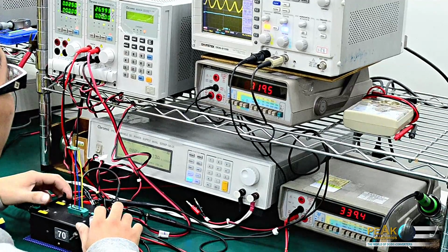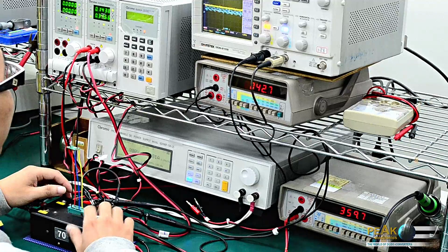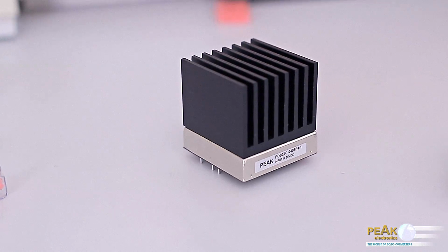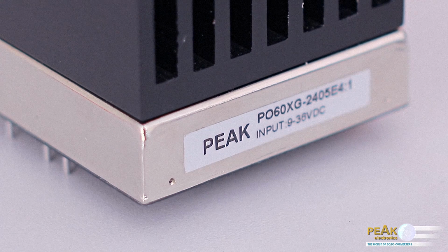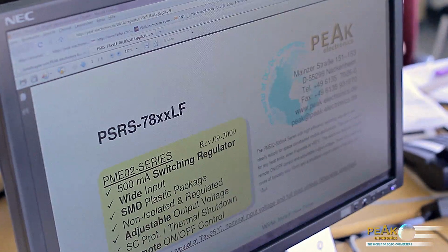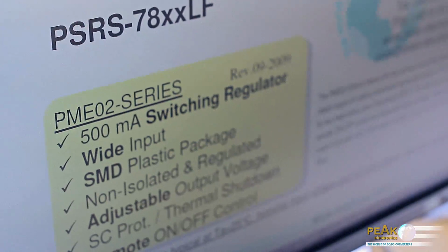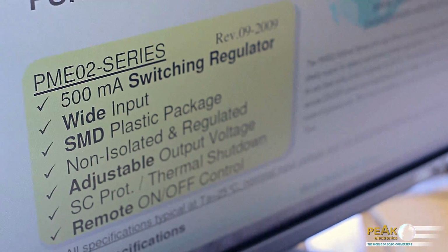The greater the difference between input power and output power, the greater the power loss, and thus heat dissipation that occurs in the converter. The converter can only transfer this heat to the surrounding environment through its outer surface. What is important is that the DC-DC converter does not become too hot inside. With regard to the specification in the datasheet for maximum ambient temperature, this value is purely a guideline value.